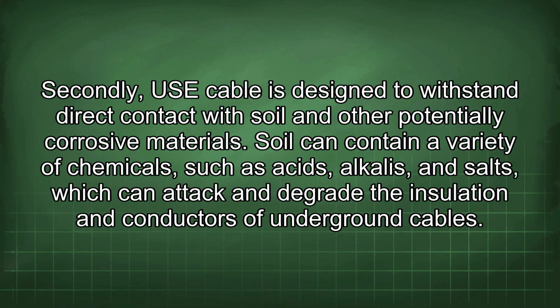Secondly, USE cable is designed to withstand direct contact with soil and other potentially corrosive materials. Soil can contain a variety of chemicals, such as acids, alkalis, and salts, which can attack and degrade the insulation and conductors of underground cables.